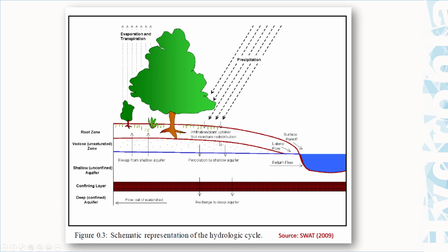Well, then this process, the infiltration process, is probably the most important process to define the most important component for the HydroBID flood model, that is the surface runoff component. When the intensity of the precipitation is greater than the infiltration rate, the surface runoff process is going to start. It's the beginning of the surface runoff process. For that reason, the definition of the infiltration process is very important. And to do that, we need to know the most important characteristics of this zone, that is the unsaturated zone of the soil.